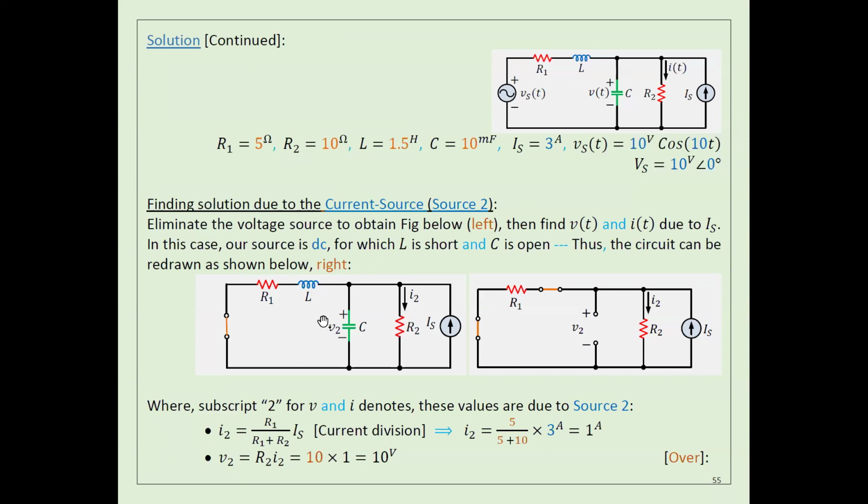Okay, so here, because the input is DC, now the inductor is a short circuit and the capacitor is an open circuit. Now you can find anything you want. If you look at this circuit, it's a very easy circuit.